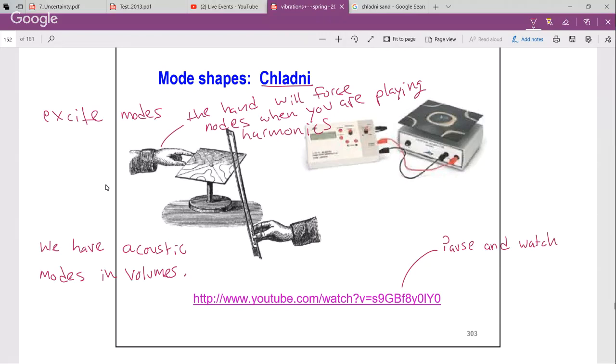The nodal points in an acoustic mode are low or zero values of sound pressure. If your ears are really hurting, you're not anywhere near a node. You're where sound pressure level is varying the most.